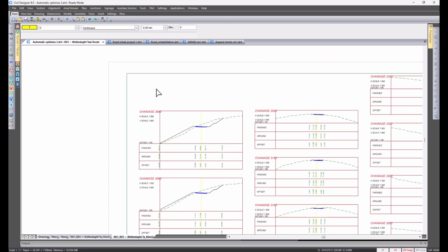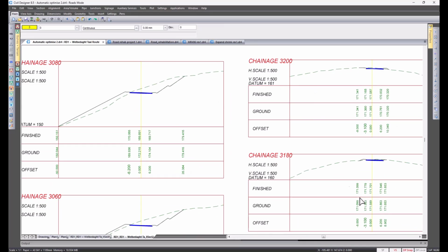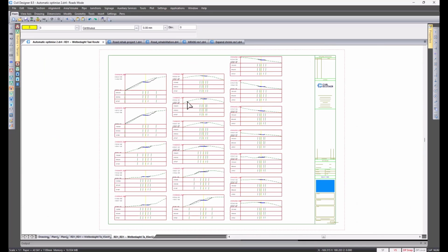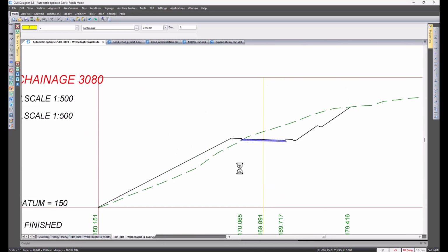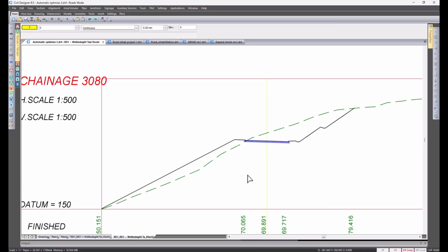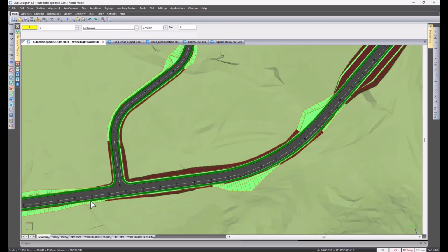Kind of slightly wider cross sections. You can see your toe lines. Okay, so I just viewed the cross sections. You can see currently that is what the program is going to use to plot cross sections and then to calculate your road volumes, until you go and reapply your template again to this design.